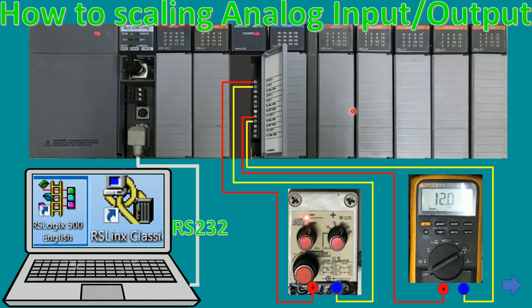Today I would like to show and share how to scale analog input and analog output of PLC SLC 500. Okay. So before going to create the program and scaling, let me explain a little bit about the wiring. And I will use the software RS Linx Classic and RSLogix 500 to configure and create the scaling.